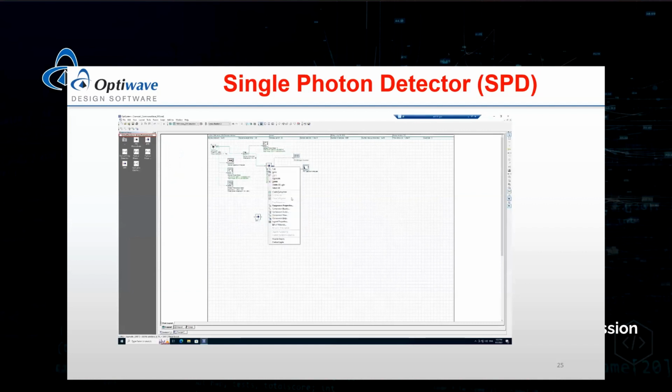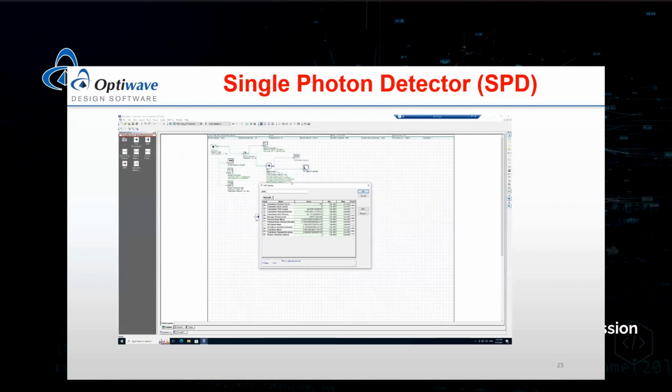And so you'll see if I go into the results, what we can find are the cumulative or the accumulation of many different amounts of photons. So photon counts, dark counts, total counts, thermal photons, and shot photons, as well as the average photocurrent and the mean and standard deviation of all of the different noises. It also shows you the photon collection method to ensure that you're using the proper collection type for the associated input signal.